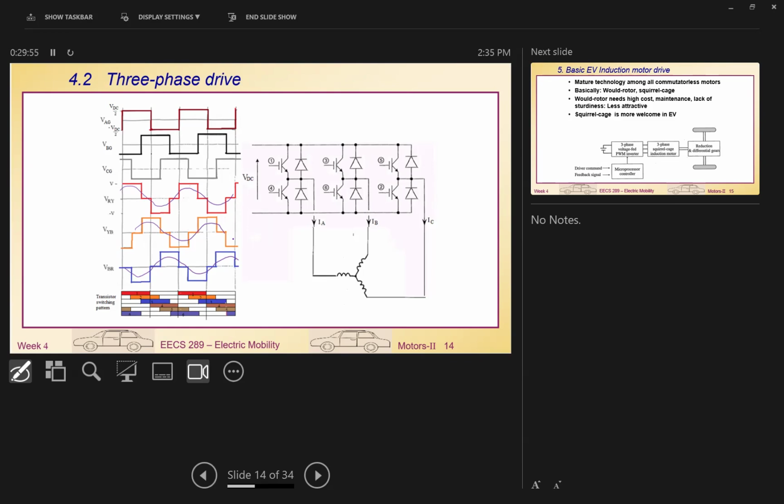You see, power electronics cannot produce a perfect sine wave. It can only produce a square wave. But that square wave gives us a really good fundamental sine wave pattern, although with some harmonics. That's the way we control an AC motor. Using this concept, you can understand why we can use power electronics to drive a motor. We are not trying to use power electronics to produce a sine wave. We don't do that. So we have battery voltage here.